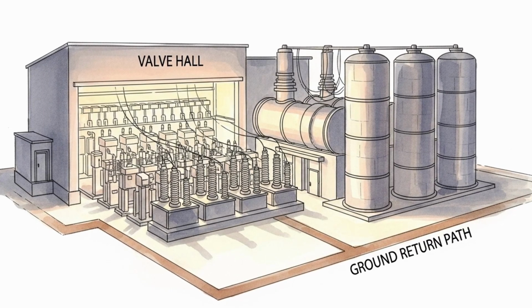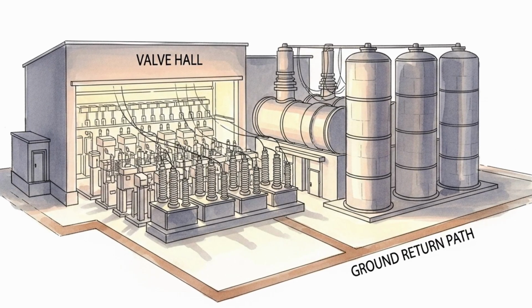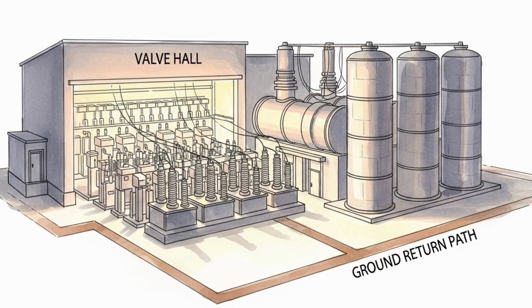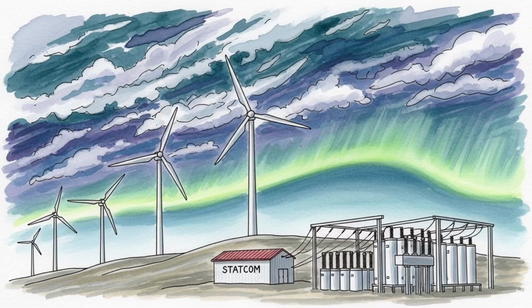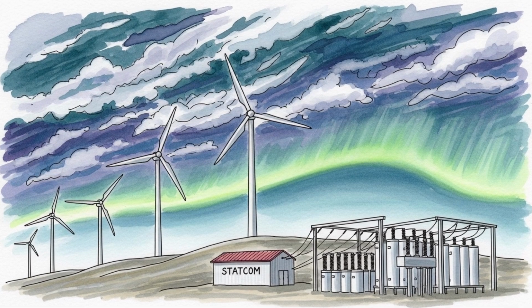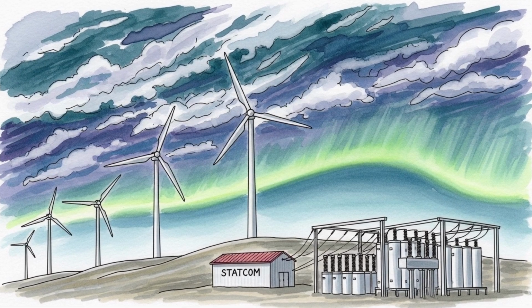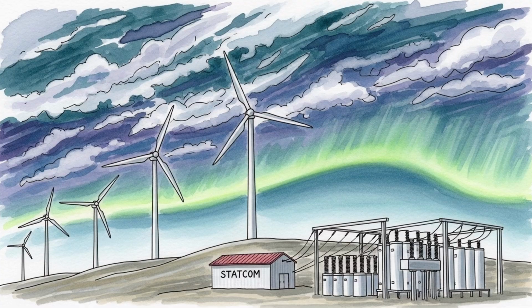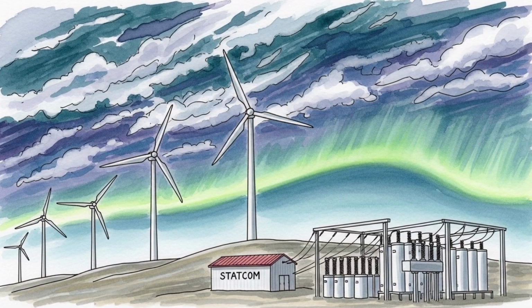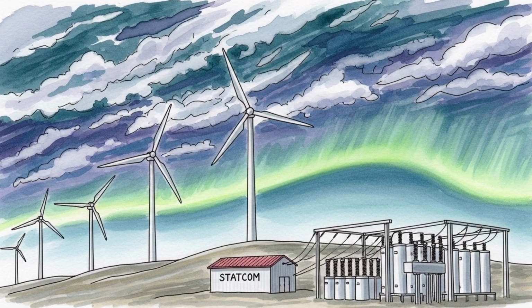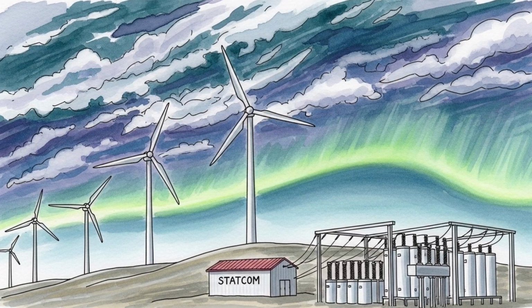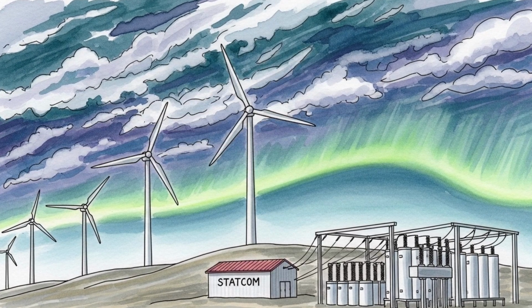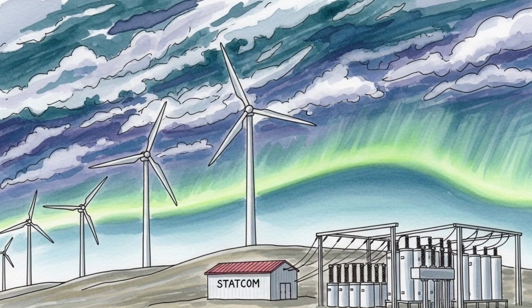Charging is a second mechanism. In geosynchronous orbit and in high-altitude transfer orbits, hot plasma and energetic electrons can charge surfaces to different potentials. Differential charging leads to discharges across small gaps and damage to coatings or connectors. Internal or deep dielectric charging builds in insulating materials and can release later.